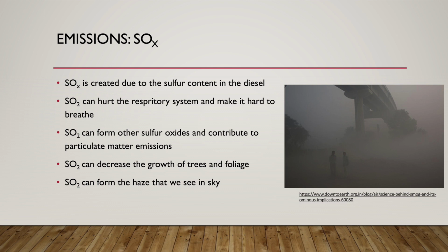So SOx is interesting because sulfur we don't have in gasoline fuels. And so when you go to the diesel pump, you'll see that it's ultra low sulfur diesel. And that is because we don't want SOx to be created. SOx is also created the same way when you have really high temperatures, just like nitrogen. And the thing about SOx is it's also treated as SO2 by the EPA.